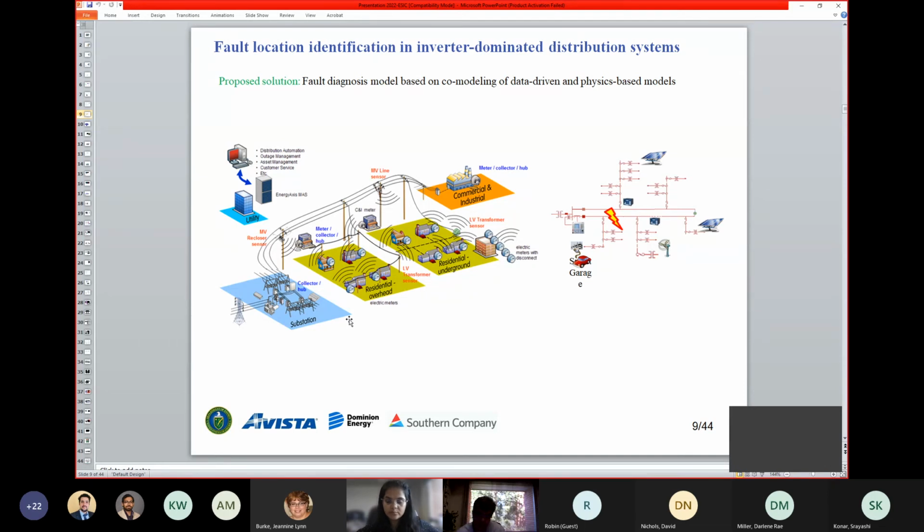So you should see where the scenarios you are studying are. If it is close to wind farms, then you have to have a detailed model. If it is further away, you can have an aggregated dynamic model. But how to aggregate that? That's one of the projects that we are doing. Basically, in that piece, how do we still limit the computational burden but still get an acceptable result?